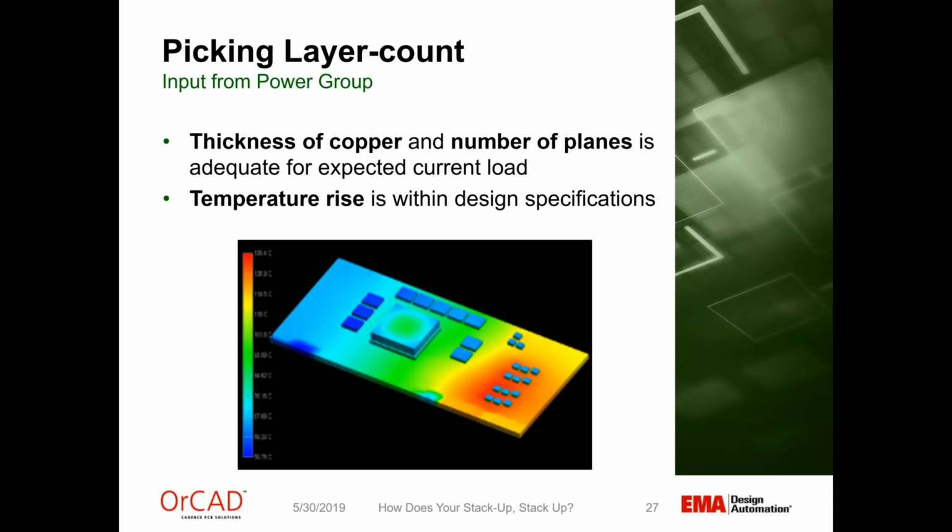The input from your power group as well, they're going to have some requirements on your stackup. They're also going to want probably lots of power and ground layers, and they're probably going to want thick copper on those so that they have fewer thermal issues to worry about.